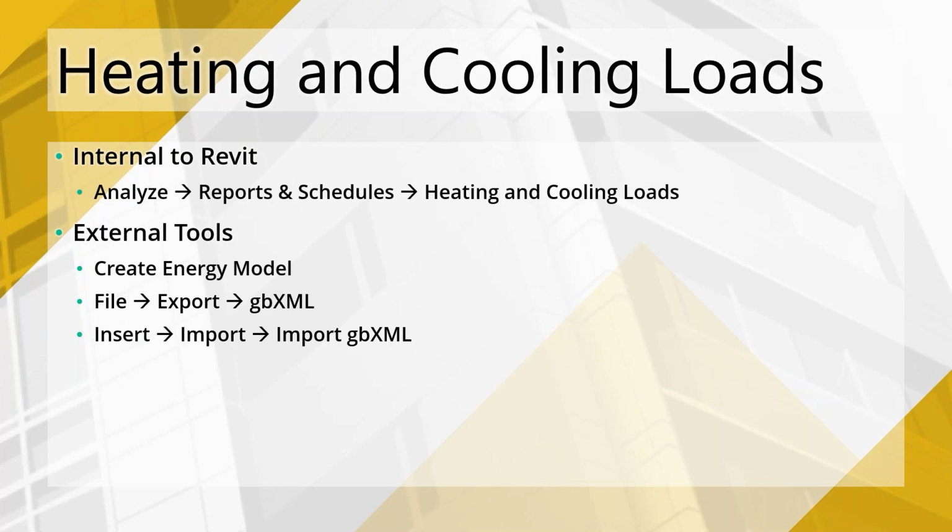Now, this takes you off the Analyze tab that we've been on all day. That's totally fine. It's just a method for you to get data out to the GBXML, run it through whatever analytical tool it is you need, and then turn around and import that back in. Over the years, Autodesk has moved a little bit where some of these GBXML import-export processes are. This is where it is in the Revit 2020 version, and I believe all the way through 24. I believe they're all pretty much the same now. It's stabilized a bit there.